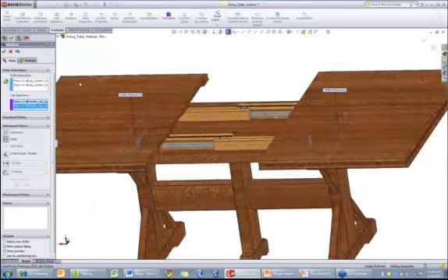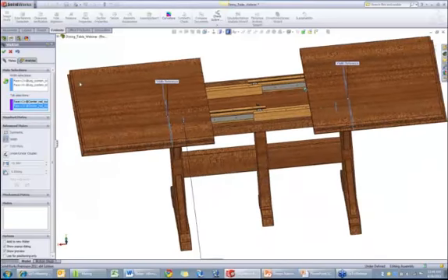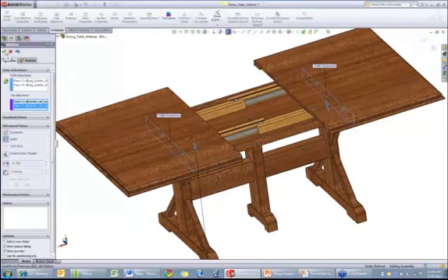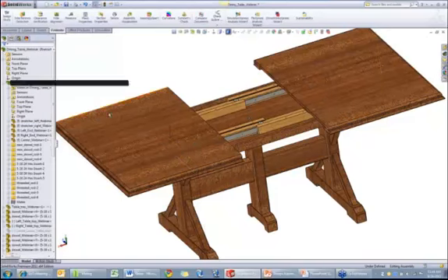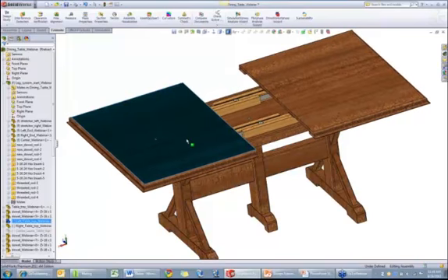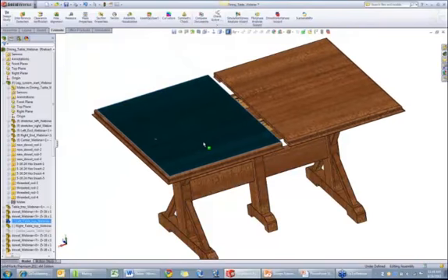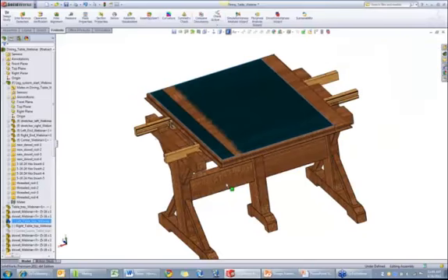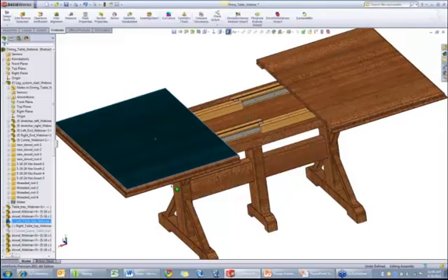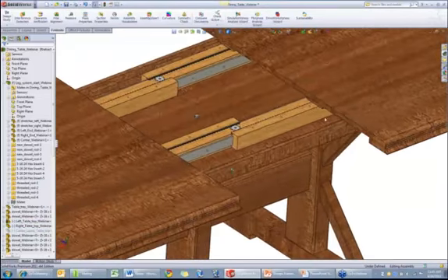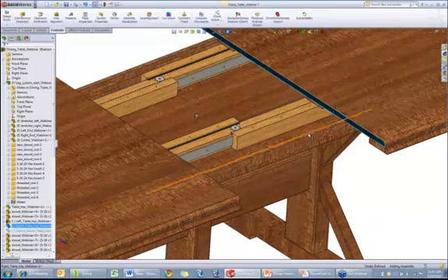And then it acts like it's just a quick way of centering components without having to use planes. So if I accept this one, you'll notice that I can now move these 2 pieces symmetrically. Now they're going to pass right through each other. Okay, so maybe what I want to do is add a limit mate as well. So I'll pick on these 2 faces. We added a limit mate earlier.